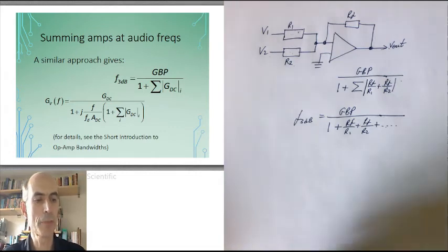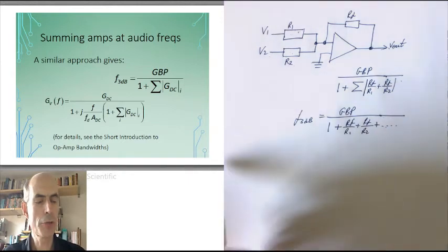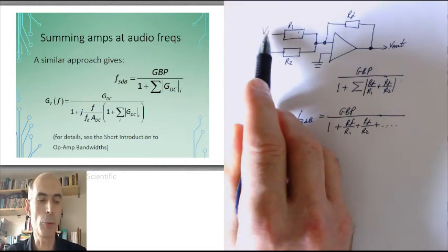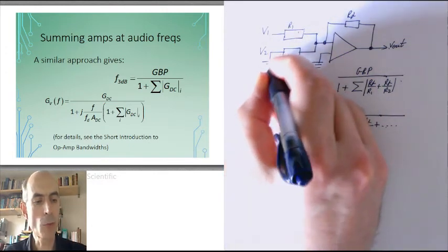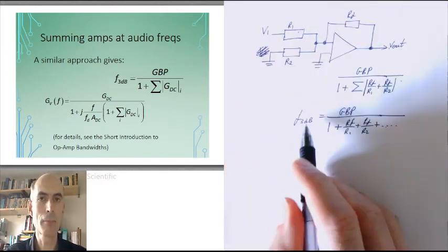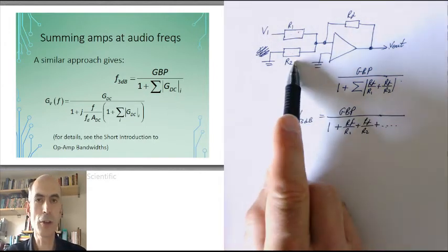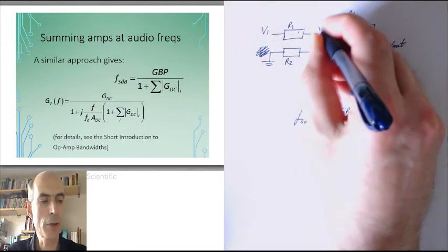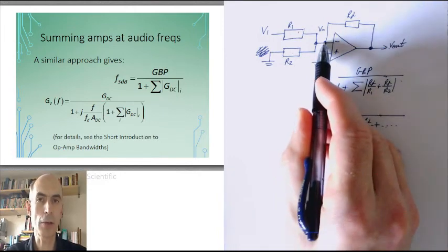It's different from a normal inverting amplifier because if you think about it in terms of superposition, supposing we only had one input that was actually being driven by a signal, we would ground the second input here. And unlike at DC, this resistance R2 now plays a part in the circuit because V-, the voltage on the inverting input here, is no longer ground.